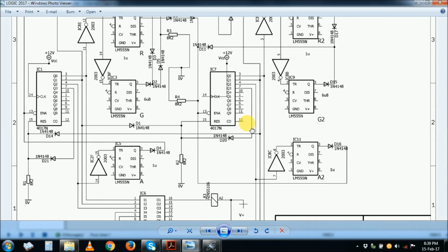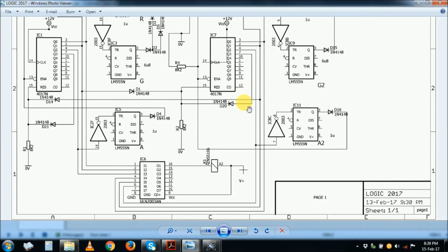Third position is our amber output. Third position is pin number 4, our amber, driving an amber relay here. So it has moved from the green relay to the amber relay, operate amber relay, and also the amber, remember, it's coming here to the timer again, a high here, trigger the timing circuit, and the timing circuit goes output high, determined by the timing of the capacitor here, high.